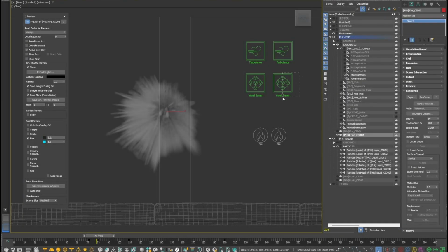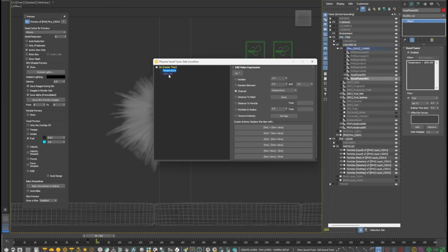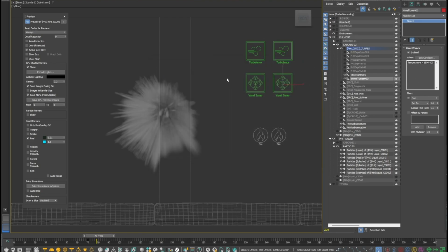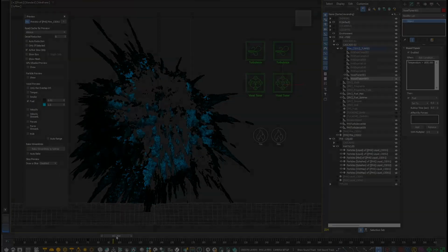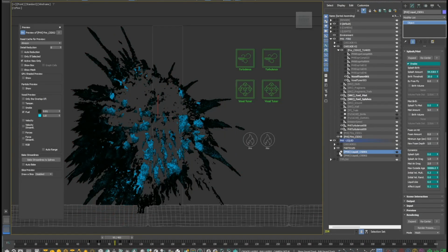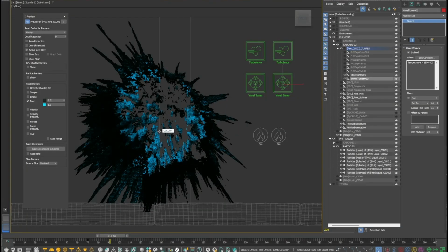The second voxel tuner in the scene is more of a tweak. It deletes the fuel by setting it to 0 when the temperature reaches 1800 kelvins. Normally, the burning process will deplete the fuel naturally, but remember, there are particles underneath that are constantly brushing and adding more and more of it. So this simple rule set by that tuner says, when it is hot enough, that's it, no more fuel. This helps create this spot in the middle that grows and eventually forces the depletion of the fuel.